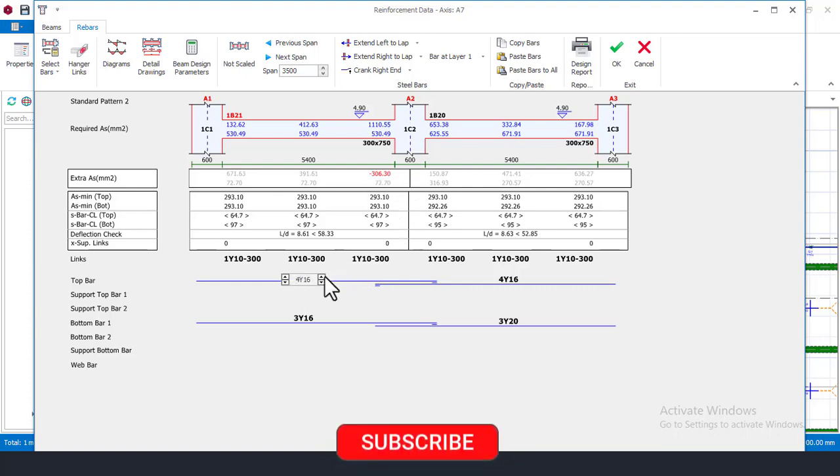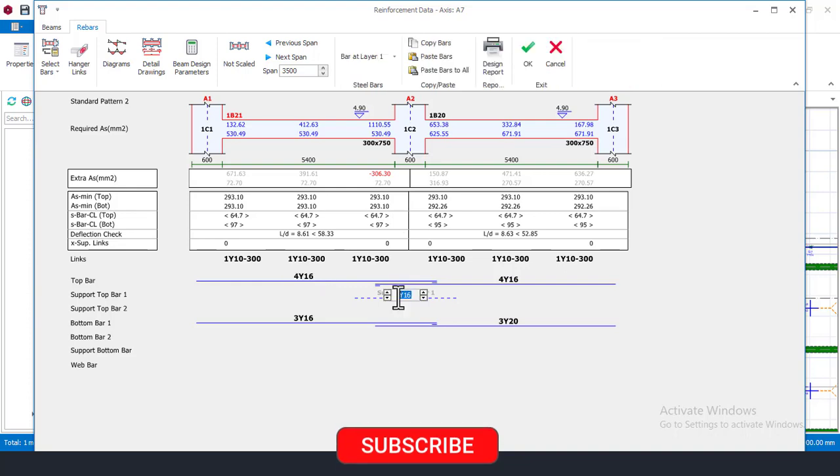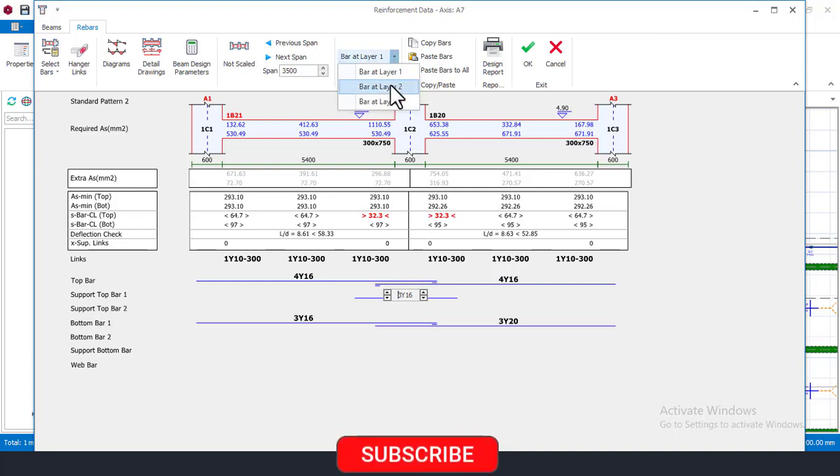I can choose to use Y20 and then Y20 here and all that. But if I don't want to do that, I can still come back and then reduce what? To Y16 and Y16 here. Now, since there's a failure at this place right now, I'll now introduce a layer 2 support reinforcement. I'll come here right now and add it up to at least make it to be 2 or 3 numbers of Y16. And then before I do it now, once you're introducing a layer of reinforcement, you must assign it to be what? To be at layer 2. So I'll come here right now and put bar at layer 2. Okay? Now I can see that it is now okay.